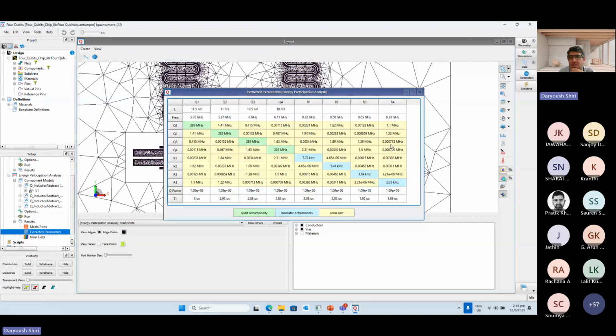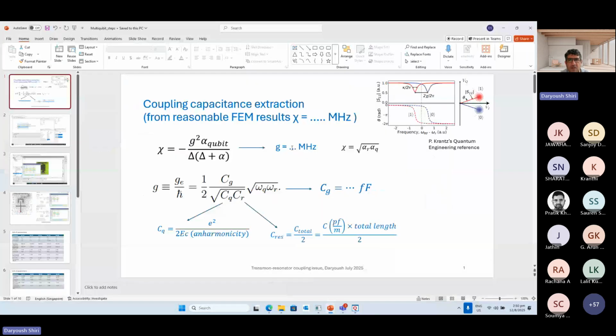So that is useful to characterize how good is your layout, if the resonators should be far apart, or which part is causing more crosstalk, and if it is an issue or not. And you will see more precise numbers. Instead of 300, you have right now 288 megahertz, 285 megahertz, and so on. So then you say, okay, what can I do with this number?